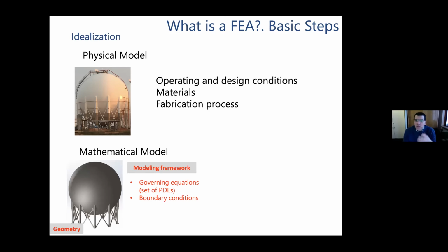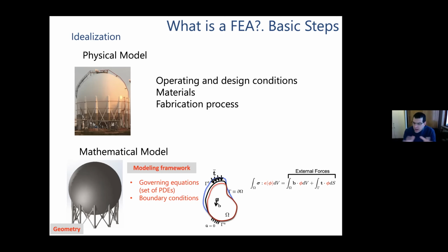For the governing equations, if you are solving an elasticity problem, a solid problem, a structural problem in solid mechanics, the governing equation in most applications is given by the principle of virtual work, which is the equation that you see there. The principle of virtual work puts into correspondence the external forces that we apply onto the solid. Those could be superficial forces or volumetric forces that will cause a deformation of my solid. So it's the equilibrium between these external forces and the internal forces that are developed inside the body. The internal forces are quantified in terms of the stresses that are represented by this sigma that you see here. And the deformation of the solid is characterized by this epsilon, okay?